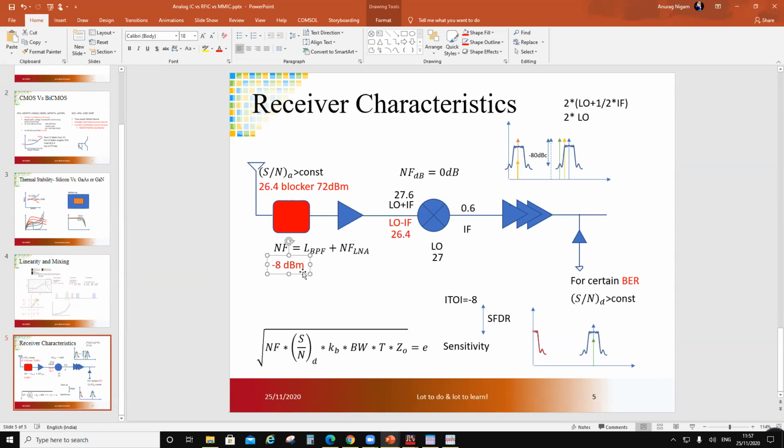So basically, let's forget this number for a second. Let's say the minimum signal strength I could receive is this sensitivity, and then there is 80 dB of filtering here. And the blocker basically can. So what is the lower limit of that? That would be the attenuation of the filter, not the sensitivity.